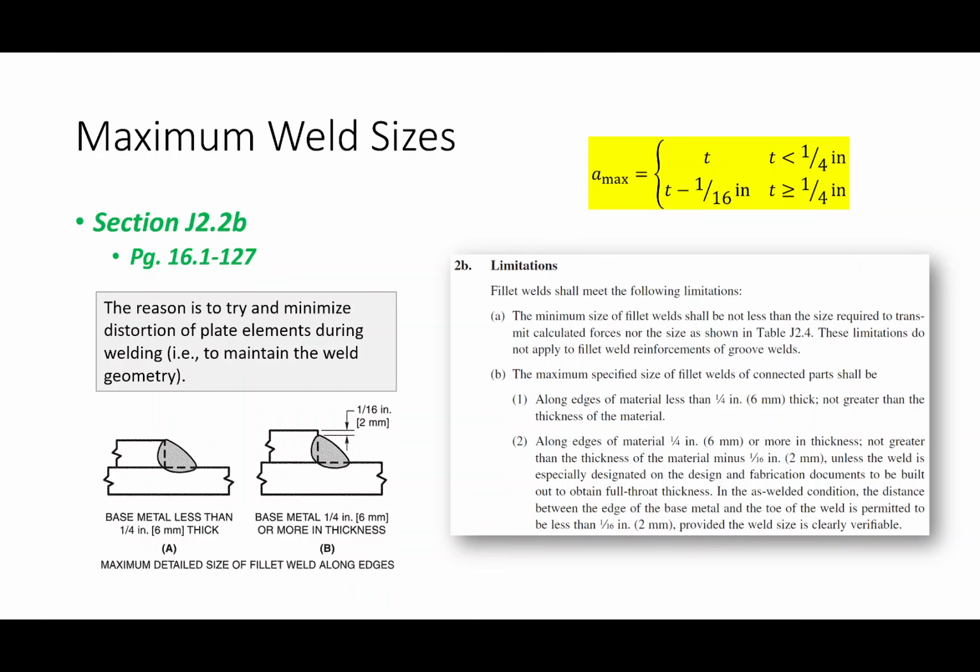There needs to be a little bit of a gap right there so that at the end of the day, when the weld cools, we can assume that 45, 90 triangle, and we haven't melted this corner of the plate, okay? And that value is a 1/16 of an inch, okay? So that's what's going on right here, is that it's saying that if you're depositing this weld, in order to maintain that geometry, you need to back this off a little bit.